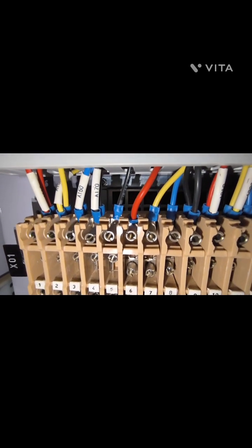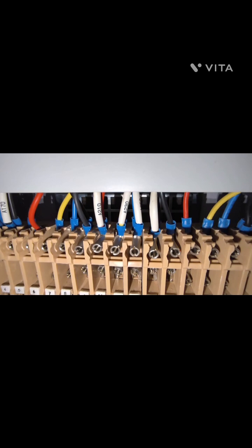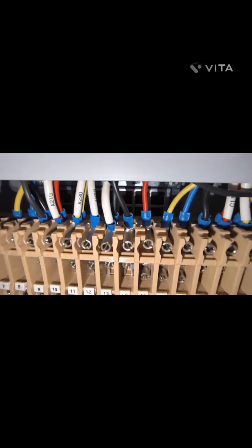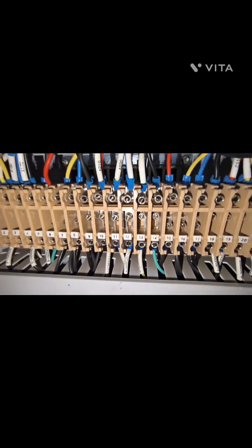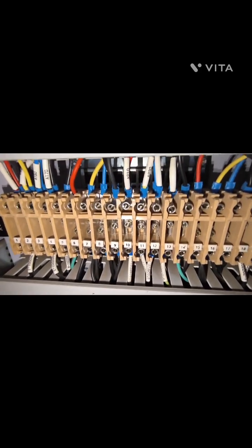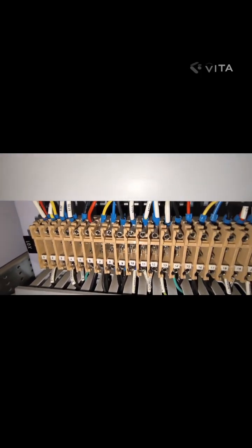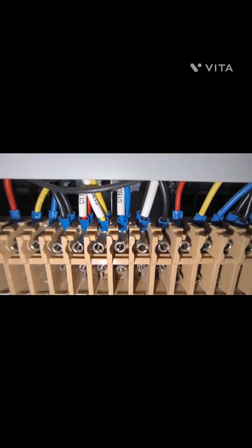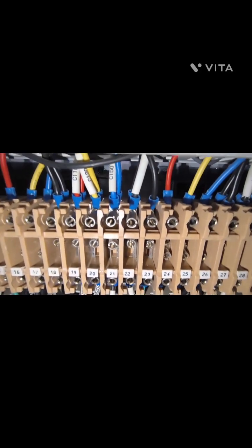A150, A170 is there. Now you can see A210, A230. This is a transformer control relay panel. So these cables are used for the primary protection, the differential protections. Now you can see here C Ferrule is there. That is for the overcurrent and earth fault protections.